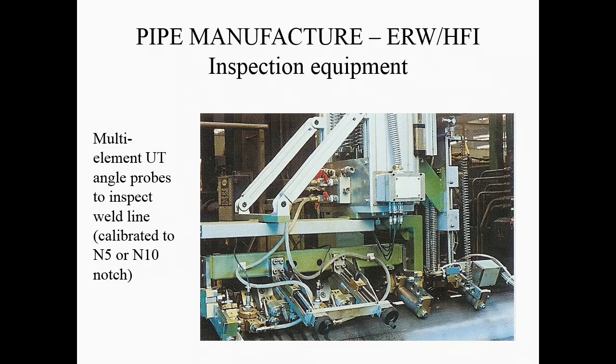So this is the inspection system for that. What we've got here is a set of ultrasonic probes, an example there, and they're lined at different positions, and this roller system which rolls along the pipe, you can see there's a guideline here. This is actually going along, and those sensors operate at different angles.